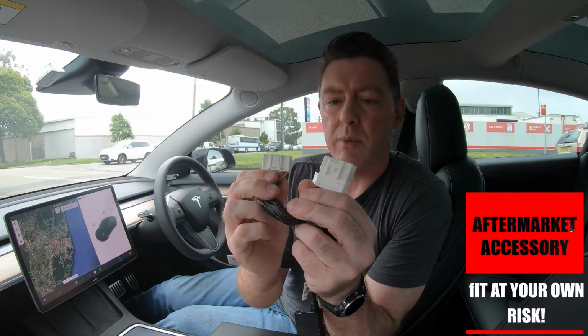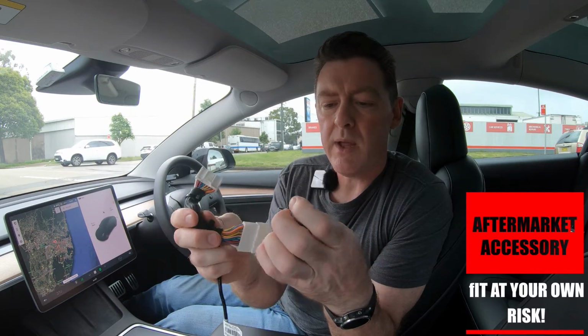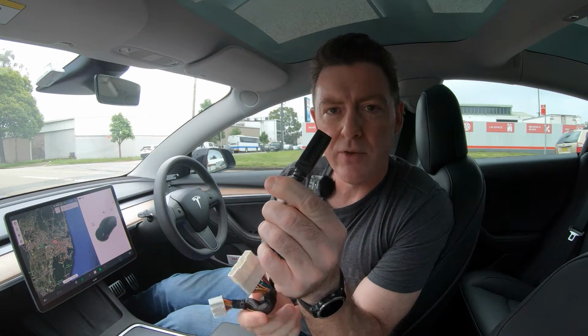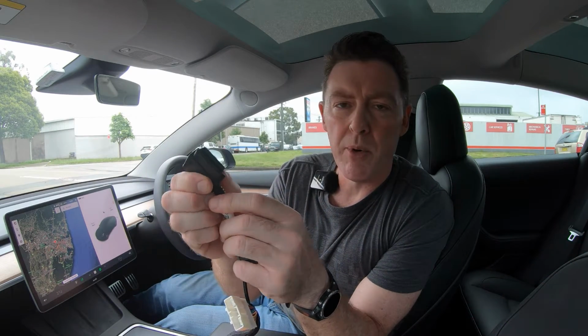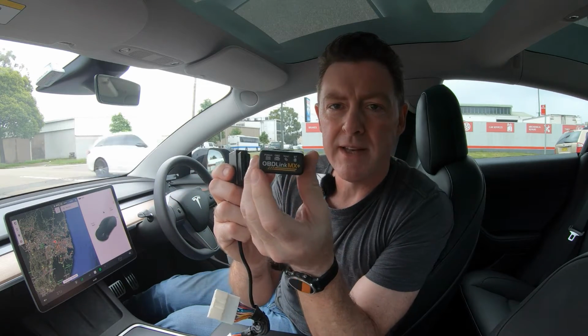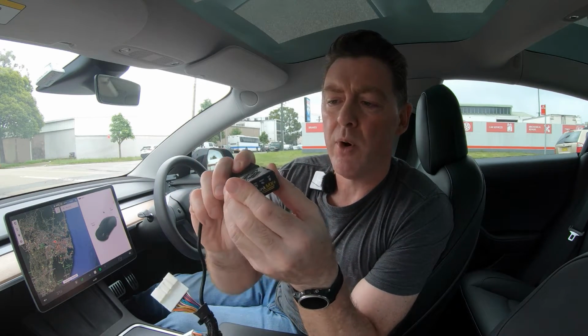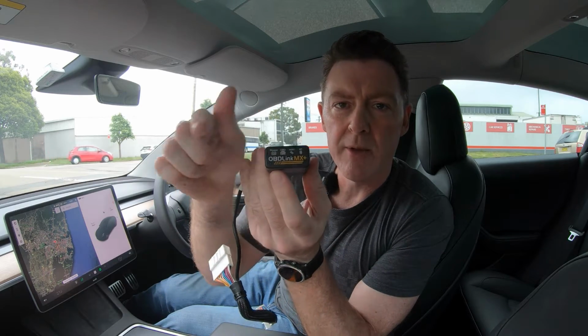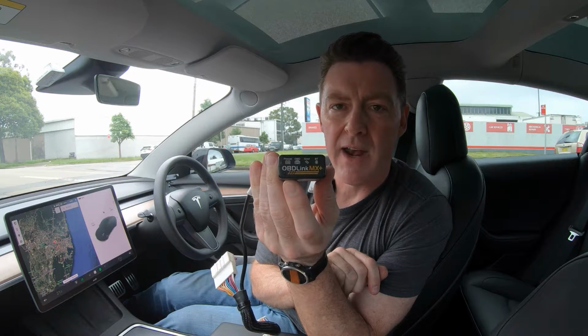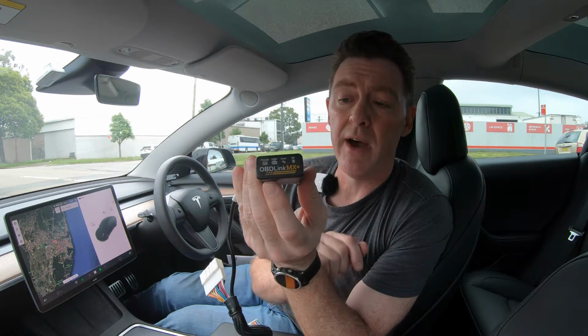We're going to tap into it with this harness, and this harness is then going to give us an OBD2 port. Now this is an onboard diagnostic port, and we're then going to plug our OBD adapter into that port. It's then going to communicate with our phone and give our phone access to read the data that's flowing around the CAN bus circuit of the car.